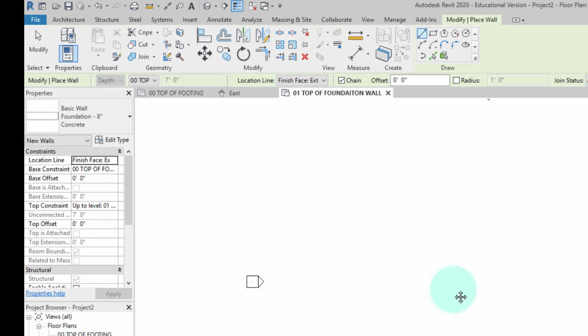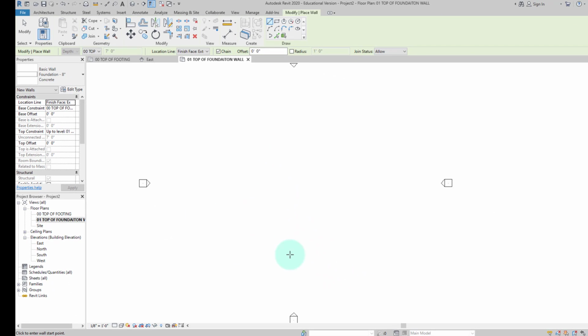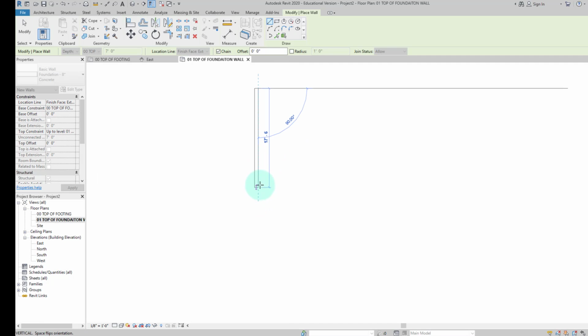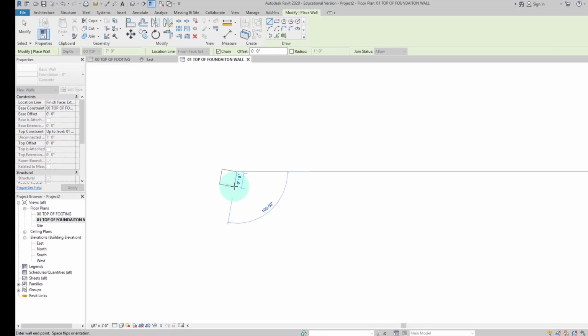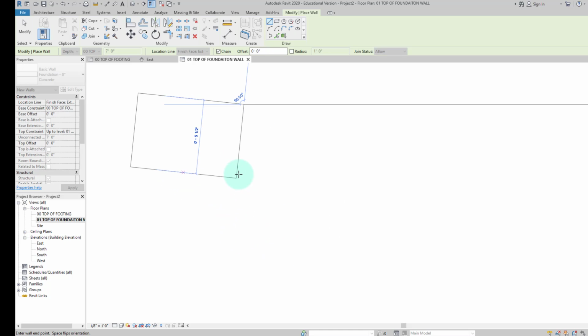All right, so this house is going to be just a box. Go ahead and click anywhere. Try to keep it towards the middle, but go ahead and click anywhere in here. And as you move, some things about Revit, as you move the cursor, you will see the little dimension will change, and depending on how far you're zoomed in will actually determine that snapping. So now I'm down to 1 inch every time I go way out here. Look at it's doing every 6 inches. If I get super close, I can get down.